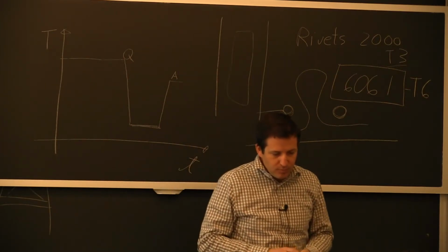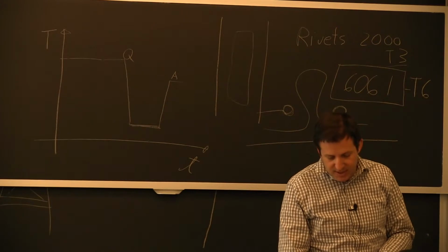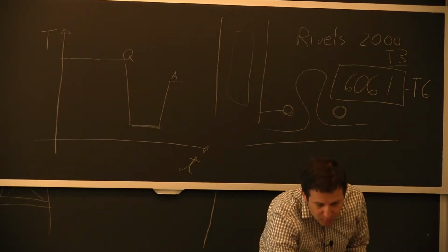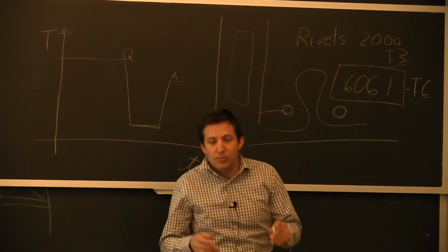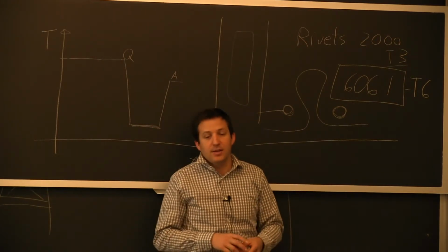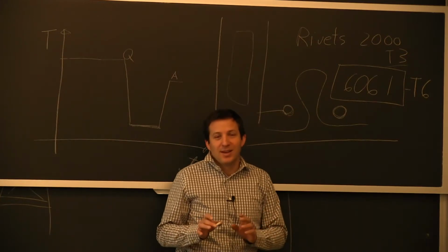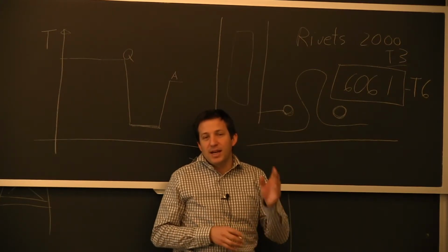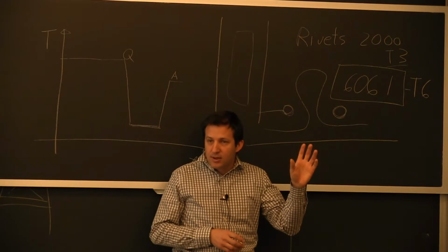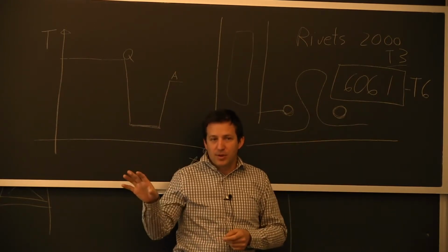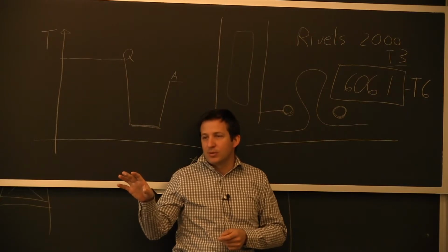So the extreme example of this that I'm aware of is, I put a range as 1.2. I haven't done myself a design of a landing gear, but I'm told that it's about 15% left. 15% between the highest stress that they predict from a load analysis and the lower strength they predict from testing the material.